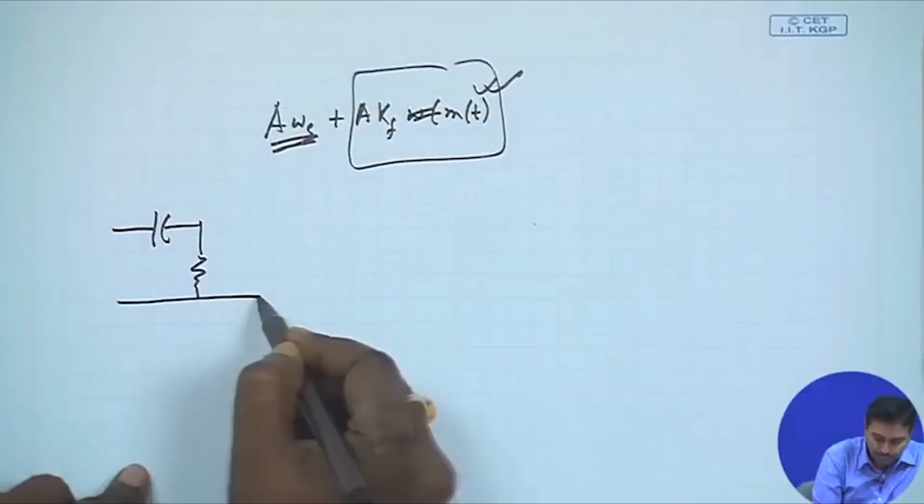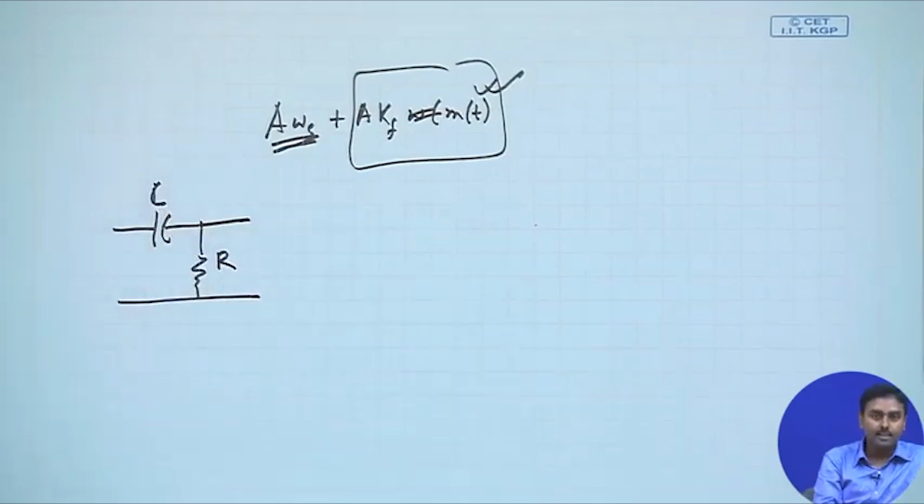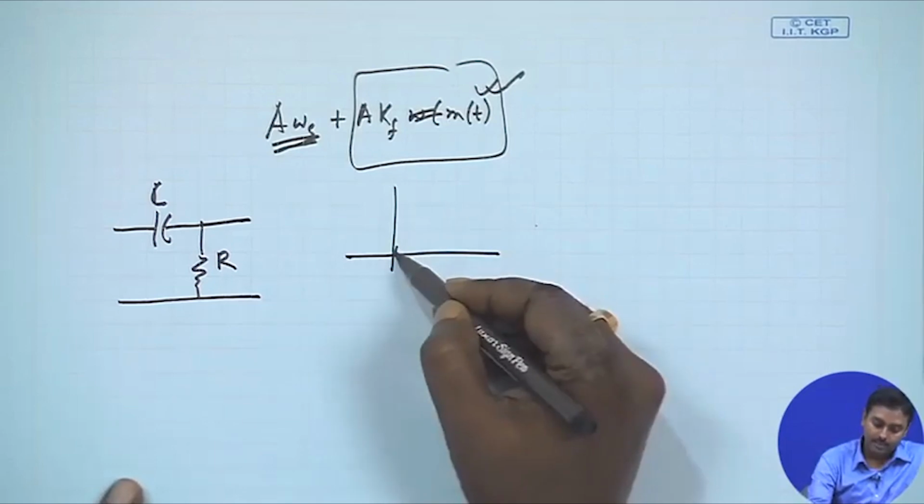Generally, you cannot actually get an ideal differentiator, that is not possible in circuitry. Every capacitor will have some spurious resistance, there will be some other effects, and you will always see that it cannot work as an ideal differentiator. There is nothing called an ideal differentiator. What we will do is employ something like this, a CR circuit. This is actually a high pass filter, right. So, how will the high pass filter look? It will look like this.